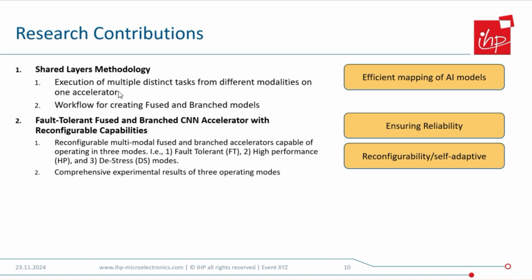This is an efficient way of implementing multiple tasks on one single accelerator, which reduces a lot of hardware resources and also energy. And then extending this shared layers approach, we propose fault tolerant, fused, and branched CNN accelerator, which can reconfigure itself in three operating modes, which are fault tolerant, high performance, and de-stress mode. And this contribution aims to solve the reliability challenge that we have for safety critical application, and also adds reconfigurability and self-adaptiveness within the architecture. And this helps us to adapt the processing system as per the application requirements.